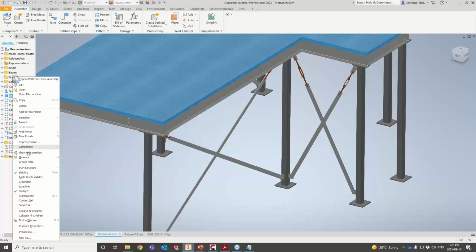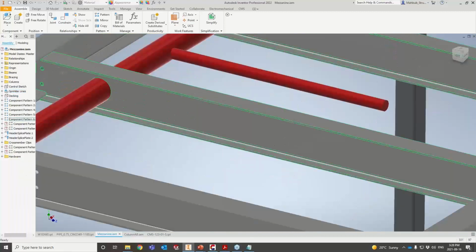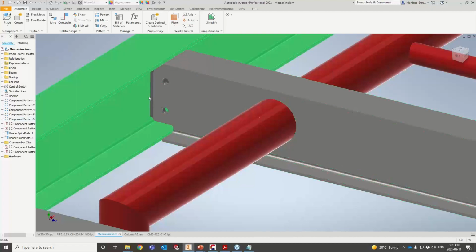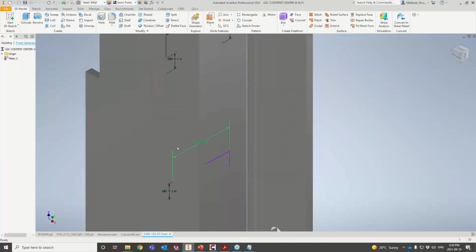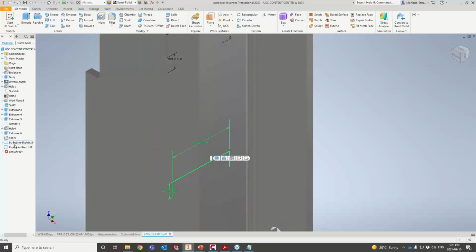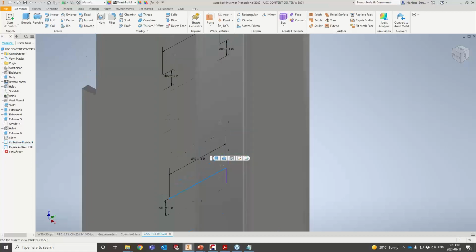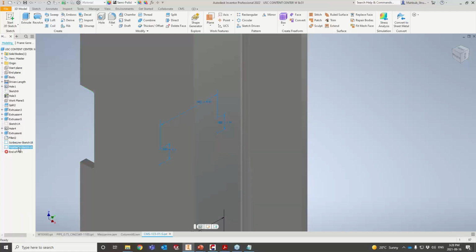So let me turn off this one. There is no way I will be able to grab that detail from your assembly detail. I have to have that marking content added manually as a scribe line, as a line content, not a construction line or something like this. And the same thing goes for the pop marks. You have to add them manually on a sketch level, and from there we'll be able to grab it.